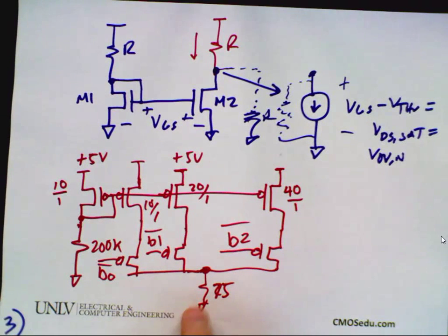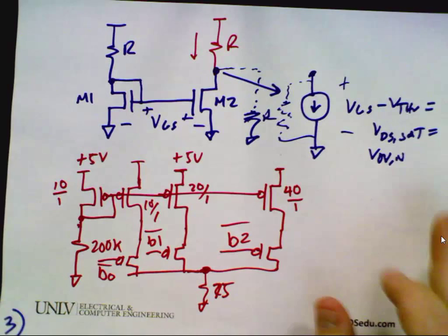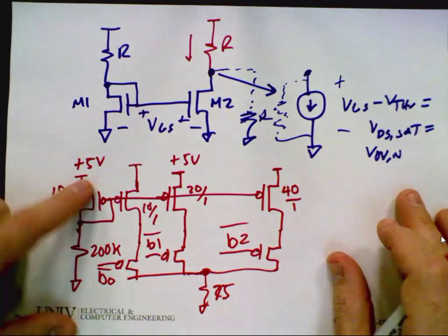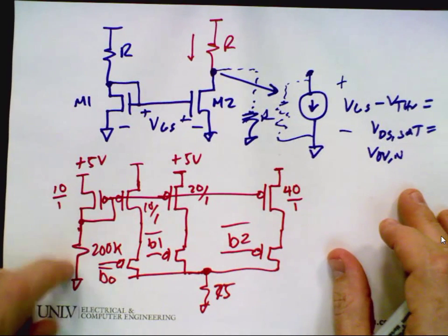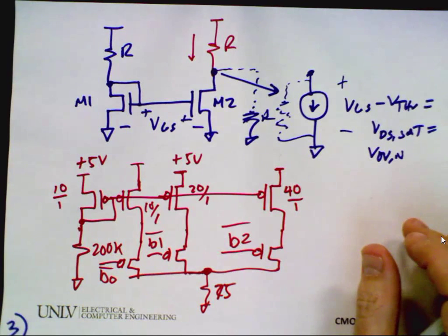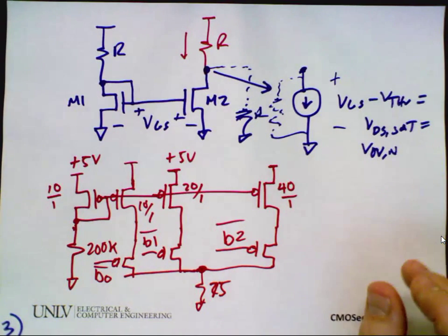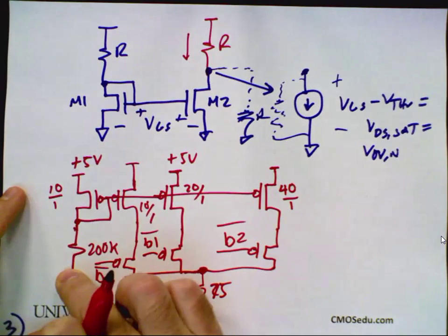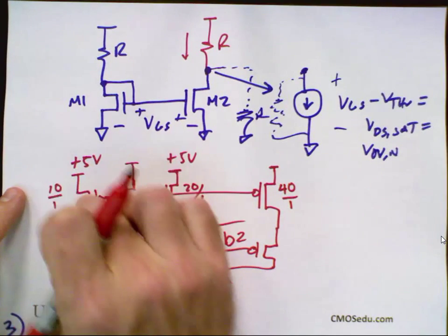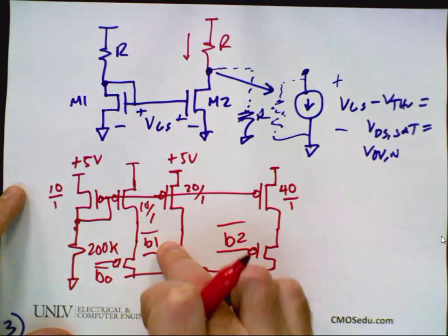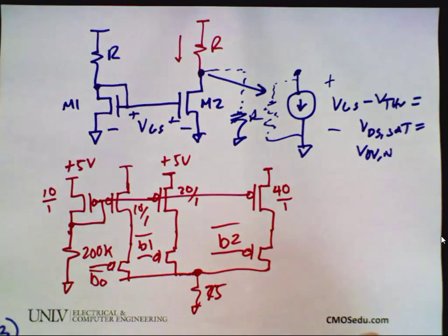So this is one reason why you would want current sources, but we'll use a bunch of other ones in the class when we make op amps. Okay, so what we need to do, and you'll have a quiz on this probably on Wednesday, is I need to calculate the current that flows in this transistor. So this is one where you need to solve a quadratic equation. So I'm going to take this part, and then I'll calculate VGS or VSG and the current. And then once I've done that, I know this will be the same current, this will be twice, and this will be 4 times when I'm neglecting what?